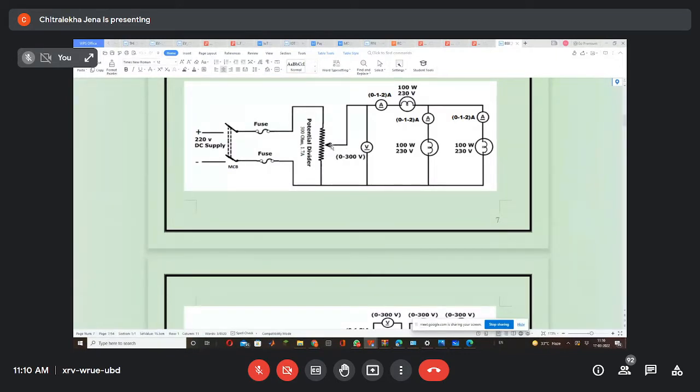Here you can change this moving point. You will change this moving point such that what will happen? Here the resistance between these two terminals will change. Okay, so when this resistance will change, the voltage will also change between these two terminals. So you have connected a voltmeter. This is a DC voltmeter. You see under V a straight line is there. This is a DC voltmeter which will measure the DC voltage. This is a DC ammeter which will measure the DC current.